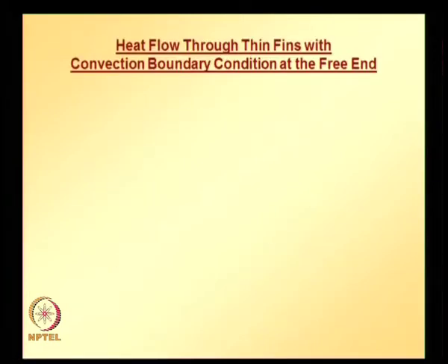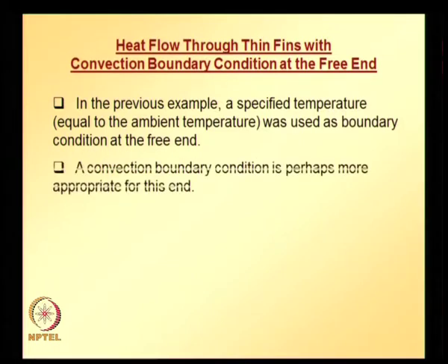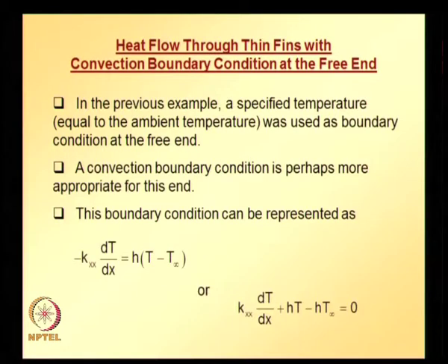So, heat flow through thin fins with convection boundary condition at the free end. In the previous example, a specified temperature equal to ambient temperature was used as the boundary condition at the free end. A convection boundary condition is perhaps more appropriate for this end. So, this boundary condition can be represented as the convection boundary condition.